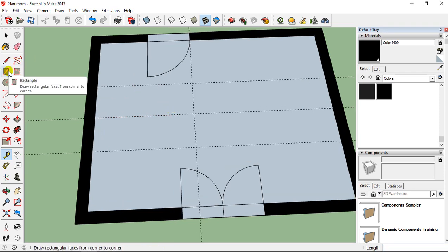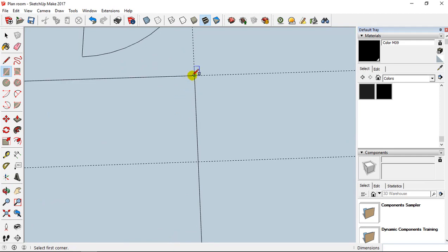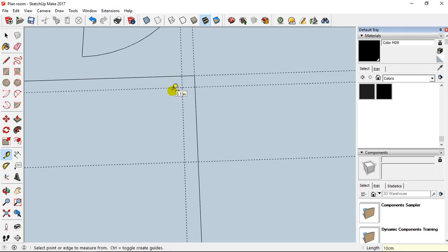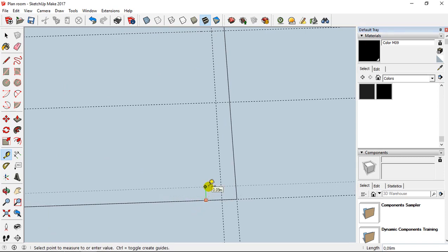And after I just take the rectangle tool and add a rectangle like this for the bed. Then if I want to change the size a little, I can also add a round corner. So to add a round corner, I can take the guide and here, for example, 10 centimeters, here 10 centimeters, and at this level I can take here, not like this, not on the edge, on the line, like this, 10 centimeters.